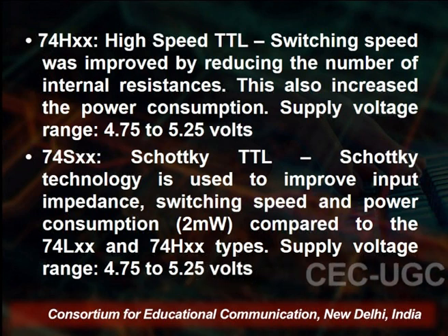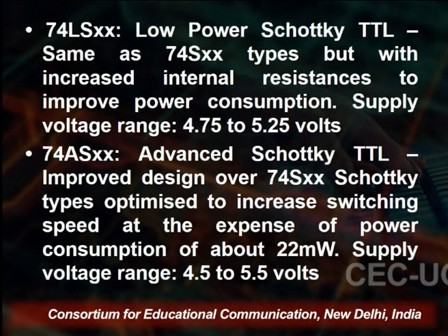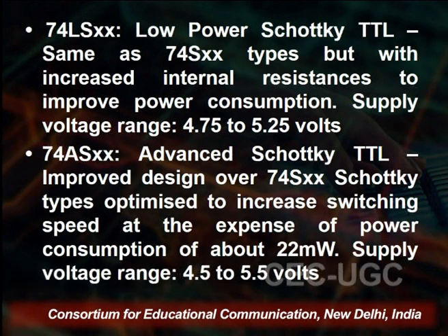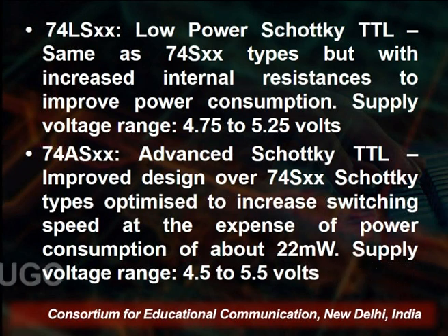The supply voltage range is from 4.75 to 5.25 volts. Next is the 74LSXX, low power Schottky TTL, the same as 74SXX types but with increased internal resistance to improve power consumption, supply voltage range 4.75 to 5.25 volts.